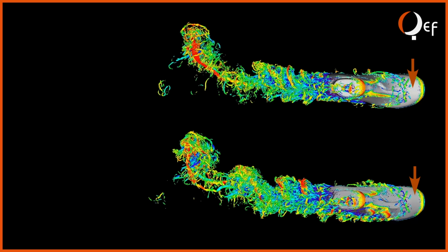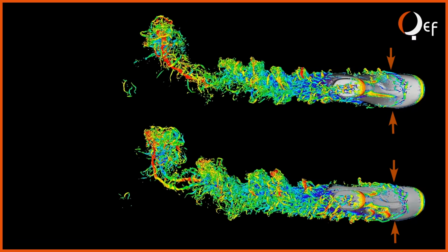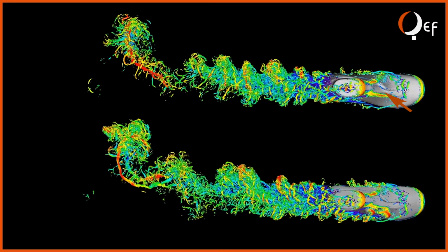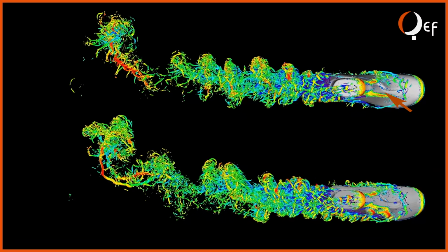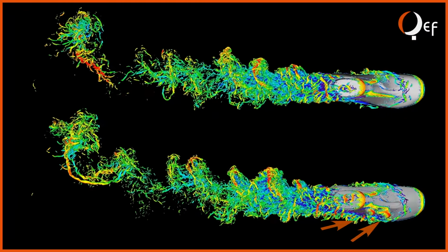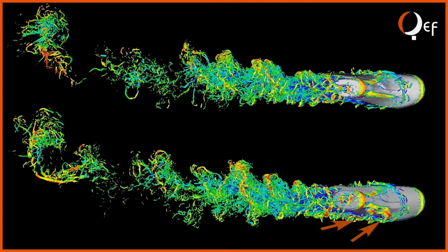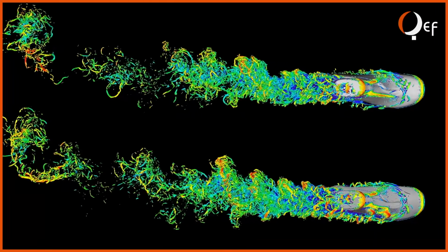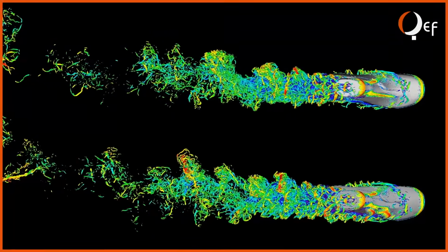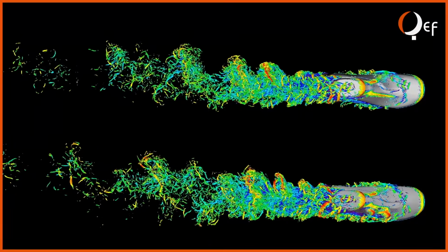The first vortices form at the tip of the shoe and split as they move backwards. The rest of the top frontal part of the shoe without BOAs does not show signs of turbulence. In contrast, vortices appear behind each dial on the bottom shoe, propagating backwards towards the wake. So, comparing the two wakes of the two simulations, the difference from the shoe without dials displayed at the top of the screen is evident.